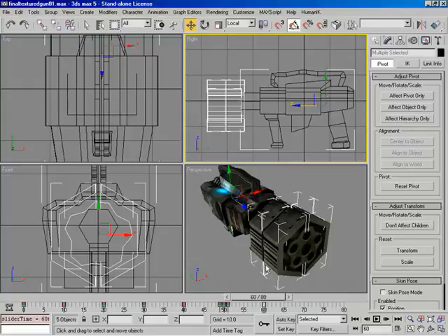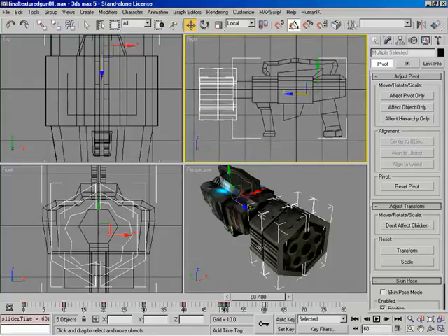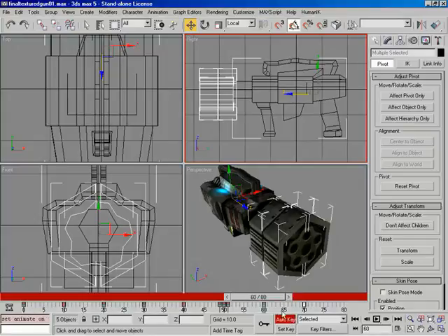So for the select, we've got the gun in its natural position right here at frame 60. So I'm simply going to move this guy, shift-click, drag him all the way over here to 70, because when we get to 70, we want the gun to be up in this position right here. So the next thing I want to do is go ahead and hit Auto Key, move over to frame 61.